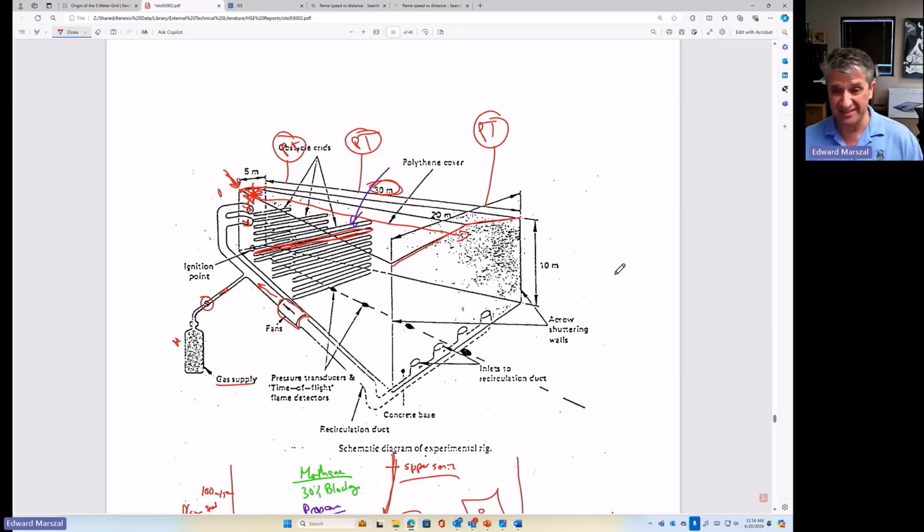That distance is 6 or 7 meters, typically, for a methane release on an offshore oil platform, which is about a 30 to 40% obstruction ratio. But if you're releasing something other than methane, you might need to rescale based on the reactivity.